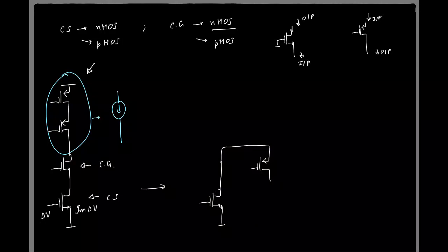Okay, if I were to use a PMOS, how will I use it? See, if I can't do it like this, this will not work obviously, because here it will look like we have a 1 by GM kind of structure. So I'll have to use an NMOS structure. The current source here I'll realize using a cascode NMOS.